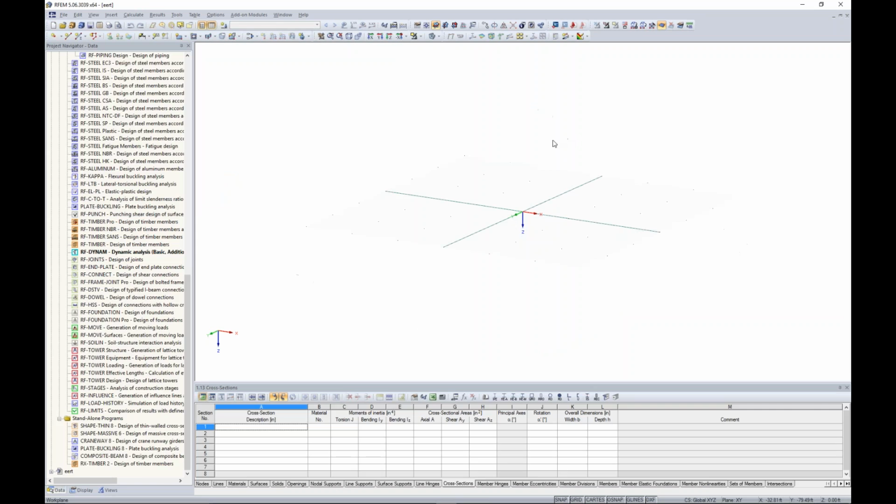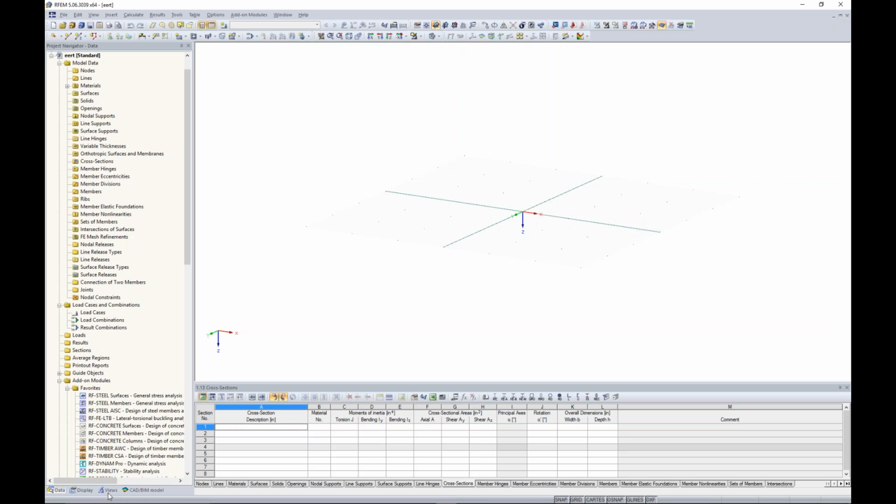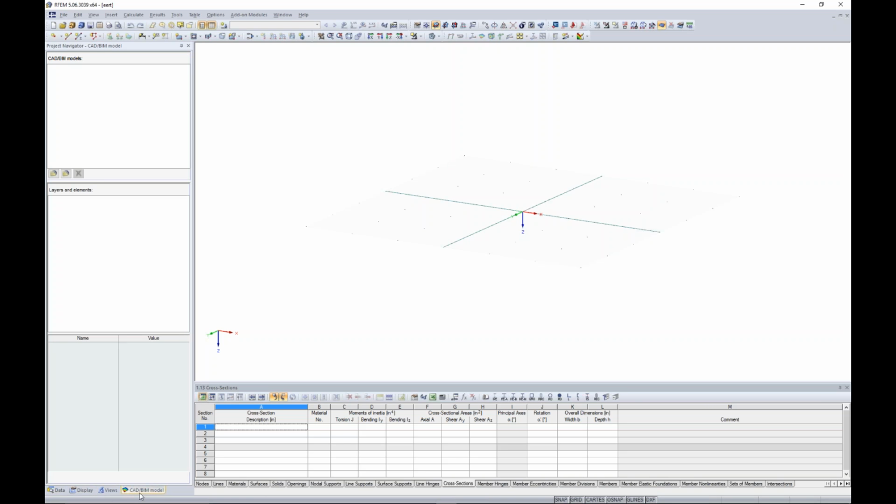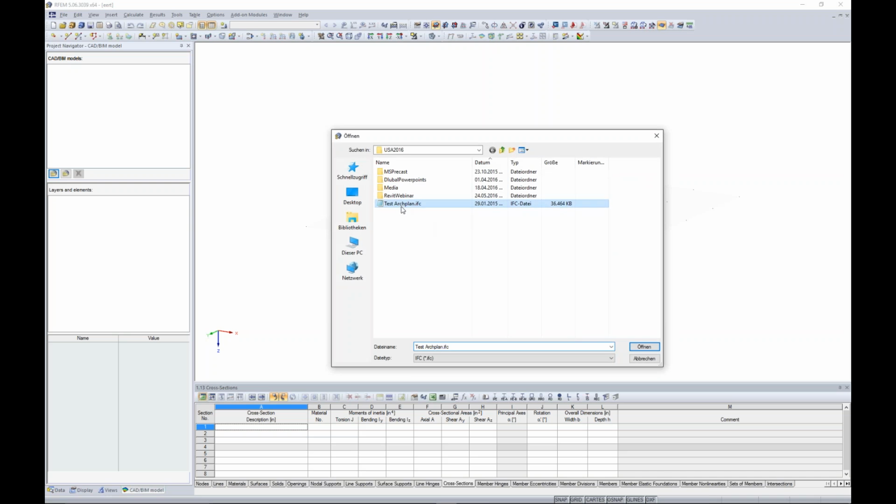And inside this CAD BIM model, if that's enabled, you have a fourth navigator here, and in here you can import IFC, or if you have them, STEP and IGES files. The difference of this IFC import is that it uses the Coordination View 2.0. We are certified as an IFC compatible software for import of Coordination View version 2.0 IFC files, which is basically plain geometry.